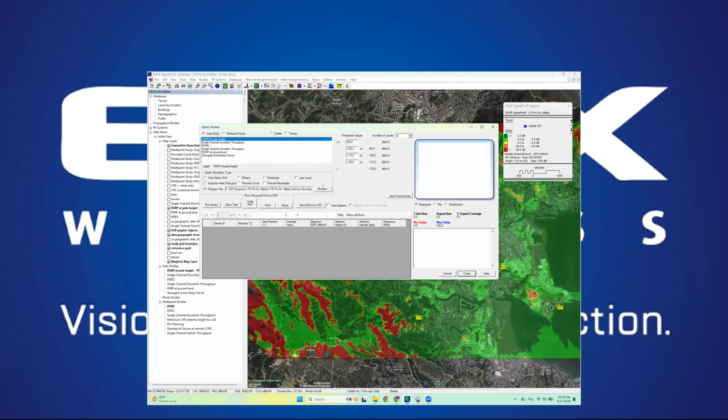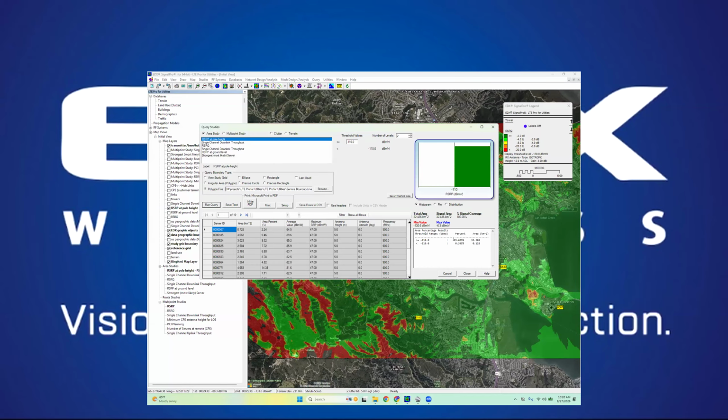So coming back in here, I've got my service area boundary file defined, and maybe I want to just set one threshold. This is my main target criteria. I need to have negative 110 dBm of RSRP across the whole study area. So I'll go ahead and highlight that and run the query. And here I can see I've got, hey, great number to report to my customer, 99.6% of the area.